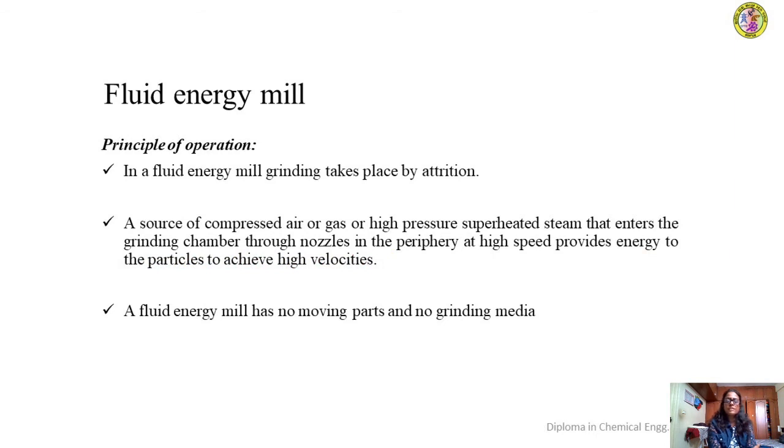So let us now discuss the fluid energy mill. One thing we should remember is all the ultrafine grinders employ attrition as a main mechanism for size reduction. So a fluid energy mill employs attrition, and to some extent impact, to reduce the size of the particles in the operation.